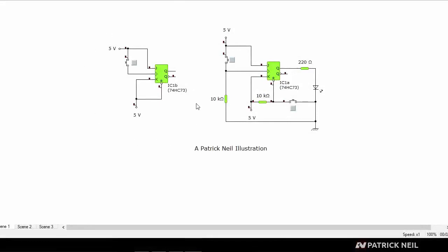This circuit to my left here is a flip-flop circuit in its simplest form. There are no pull-up resistors or pull-down resistors to switch the input from high to low or low to high, nothing like that. And the reason for that, if you have not noticed by now, is that the simulator will present a low signal on a pin if it's simply disconnected from positive power. So I do not need to physically put a ground to it. If I just leave the pin floating, it would be considered ground.